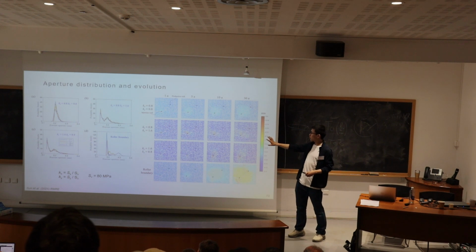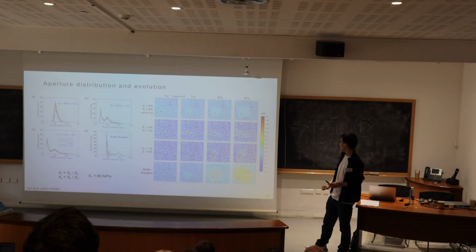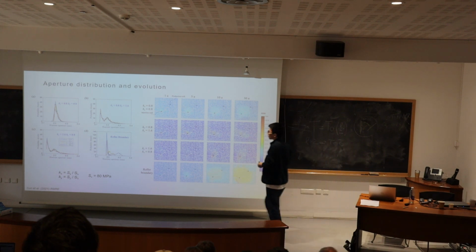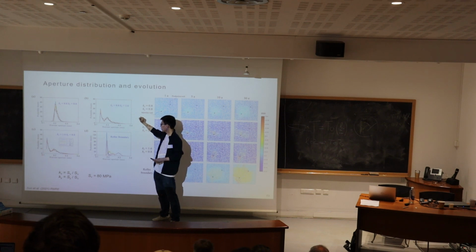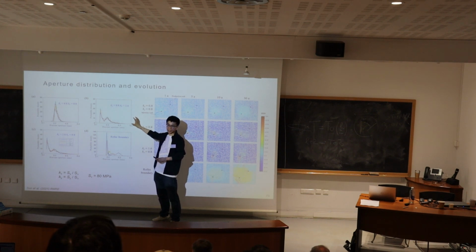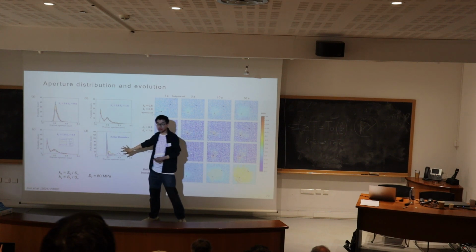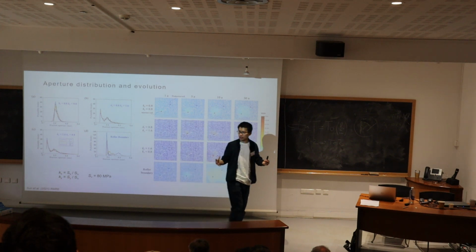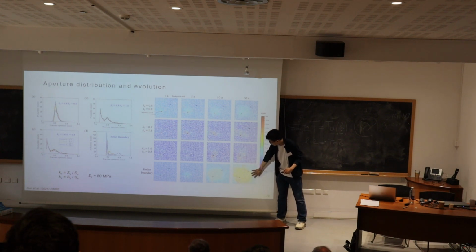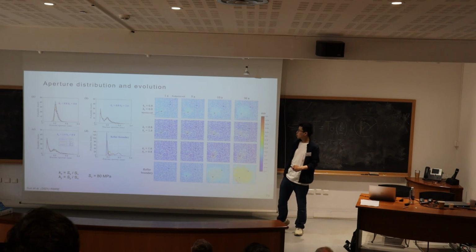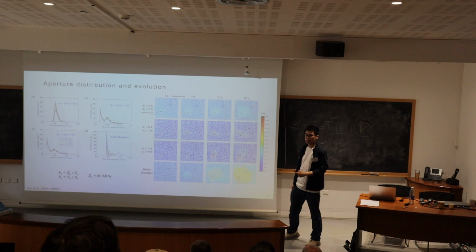And we showed that the stress can have a very important effect on the heat extraction. Conventionally, the geomechanical effect, or the stress effect, is quite often neglected in reservoir simulation. So we made a comparison with the roller boundary, where basically we don't consider the stress effect. What we found is that the aperture distribution and evolution are very different from what we see for the case with the stress effect.